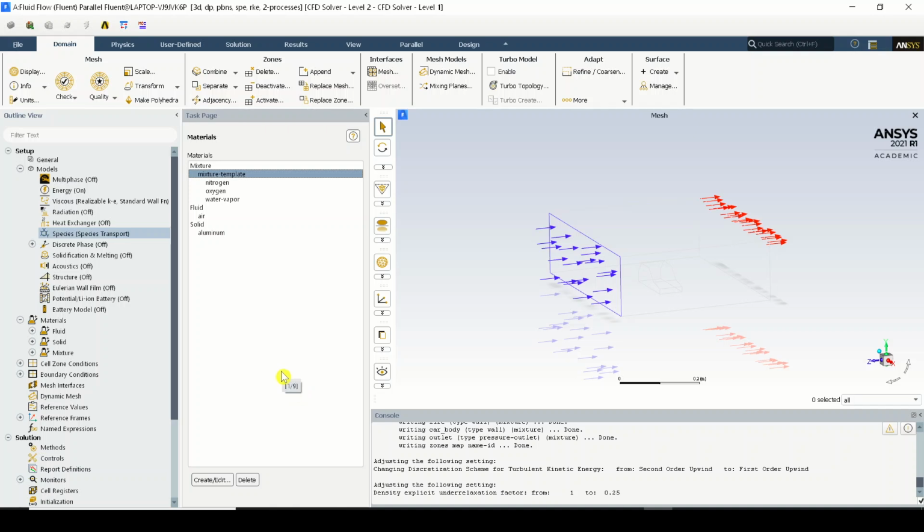So in this video, we will be adding new materials in the material list. Now, what we will be assuming is the fire which is being generated from the burner is a composition of carbon dioxide as well. Okay, so that is CO2. So we require a material which is CO2, and apart from that, for conceptual study, the walls what we have, we can just go with aluminum.